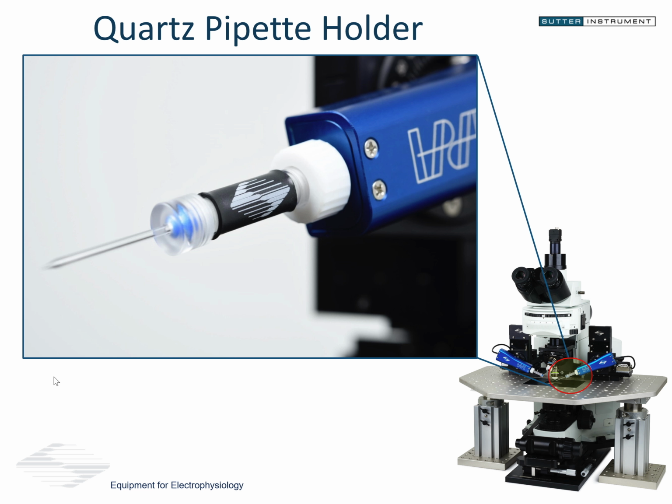As much as I would love to say they're quieter, it does not look like it. They're definitely not more noisy. It kind of makes sense since the quartz is not in touch with the electrolyte, with the pipette solution directly, or with the bath solution for that matter. So it kind of makes sense that the impact on the noise performance is a little smaller than with the pipette material.